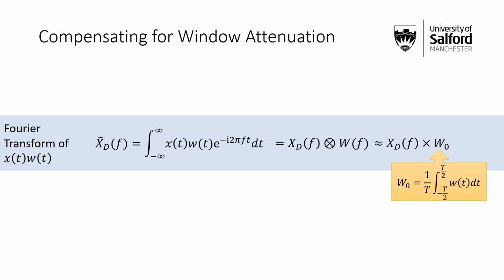So it's thrown away half the amplitude. So that is why we would see this reduced. We need to compensate for that. So we've got that factor there of a half, which we can work out quite easily for different types of windows. As I say, there are other types of windows other than Hanning windows. This would be different, but for a Hanning window it is a half.